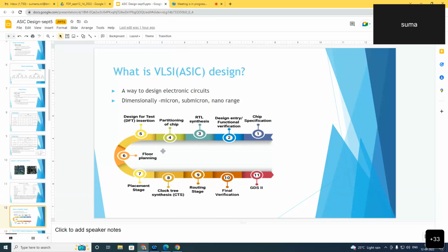As I said, we have the UPF format with respect to the Synopsys people and CPF with respect to the Cadence people. So based on that, since it is at this level, most of the things will be handled by the tools with respect to our VTs also. Whether we have to have a multi-VT, low VT or high VT, again there is always a trade-off.